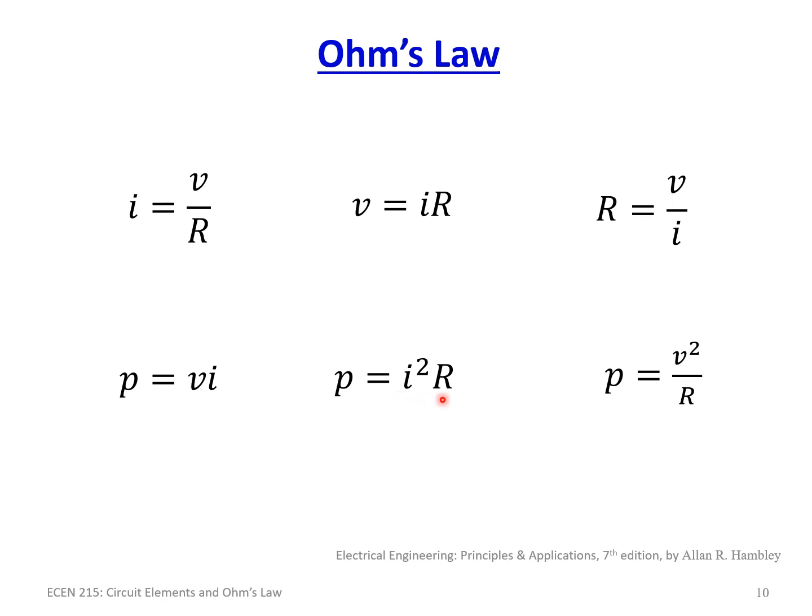If you ever wondered why they use hundreds of thousands of volts, and why so high a voltage, it's because we're trying to lower the I squared component, because the power loss is proportional to the current squared times the resistance, whereas you notice here, power is V squared over R. So if we have more current going through a line, then the more loss we're going to have in that line. So what they do is they make as good a conductor as they can, and they boost the voltage up to withstand that. And so they have insulators that can handle hundreds of thousands of volts.